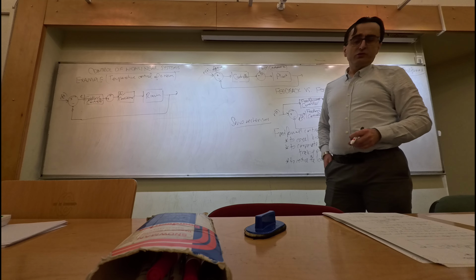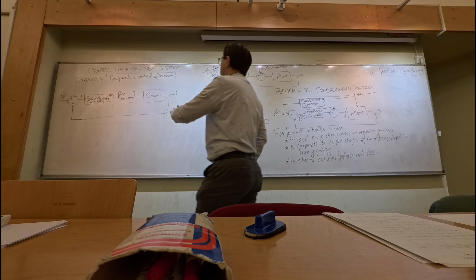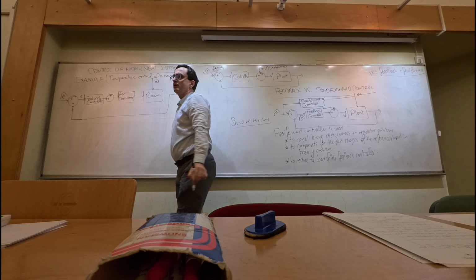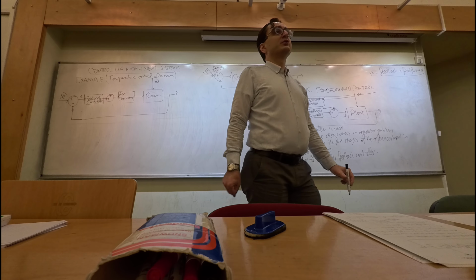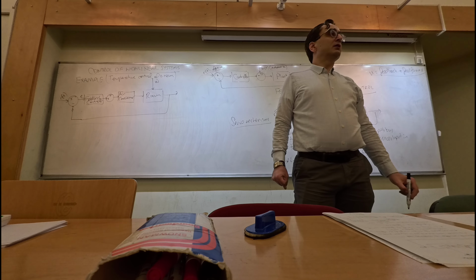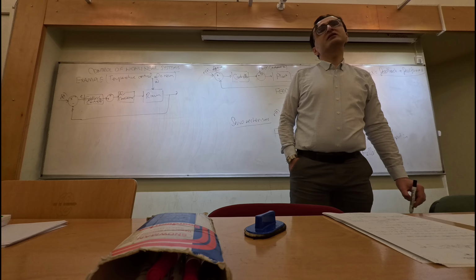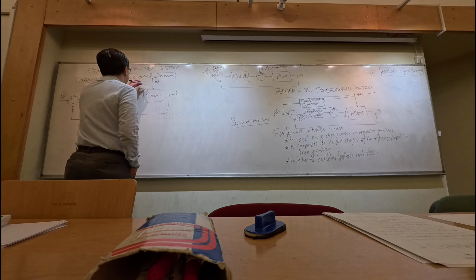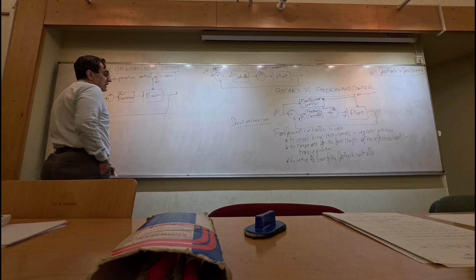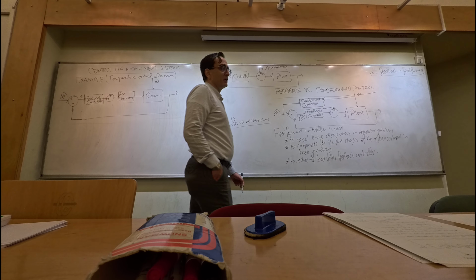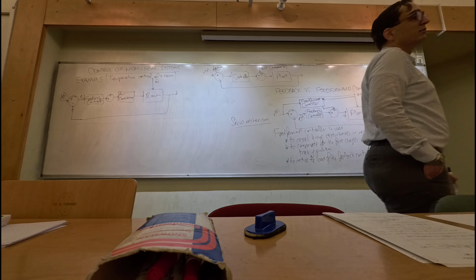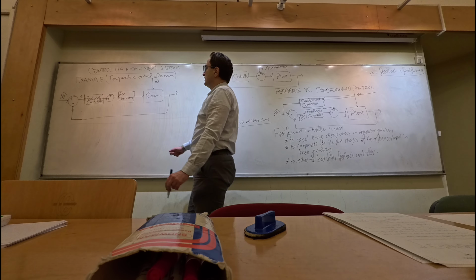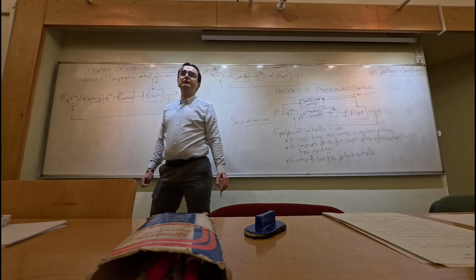And then we're going to add this disturbance signal affecting the room. It might be the outside temperature, for example. The outside temperature is acting like a disturbance on the system. And then we're going to add a feed-forward controller into this structure. So here, what is necessary for the feedback controller to actually work?